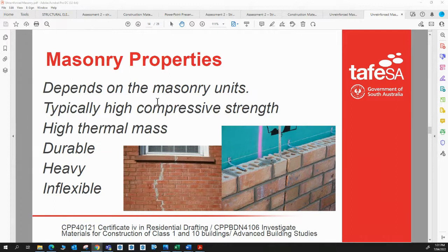Some of your building cladding systems can hide movement a lot better than your brick veneer, and that's why within brick veneer you have control joints built in everywhere to take that bending and expansion and contraction of a brick veneer wall. Within the NCC, it's AS4773 that sets out that you have to have expansion and contraction joints and articulation joints, and it sets out the various requirements for both of those types of joints.